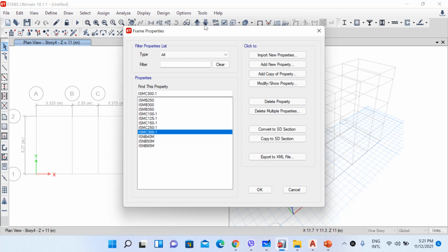Instead of designing a model and seeing if it is passing or failing under various stress checks, unlocking the model again and changing the cross section if your structure is failing, we can create a list for beams and a list for columns, and ask our software to select the optimal size from those lists itself.